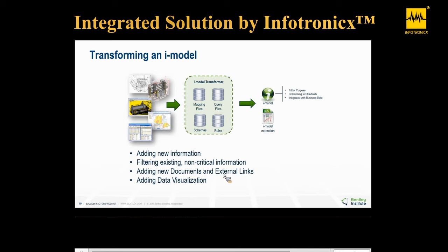So mapping information allows us to take an iModel and have it conform to a different schema or to conform to another standard. We can integrate information created by different applications to support decisions or provide some other uses, like relate data that's already in an iModel together. We can also use this for, say, inventory or reporting to develop estimates or to support purchasing, to manage tagged items or to quantify bulk materials needed for construction or for shutdown planning, this sort of thing.